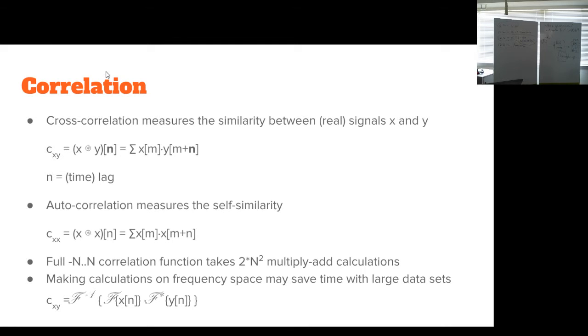Now you get the reflection back. You have the direct signal from the loudspeaker next to the microphone, and then you also have this reflection. So again you get a correlation peak somewhere here. Well, you get a huge peak here, but don't worry about that one. This is directly proportional to the distance.